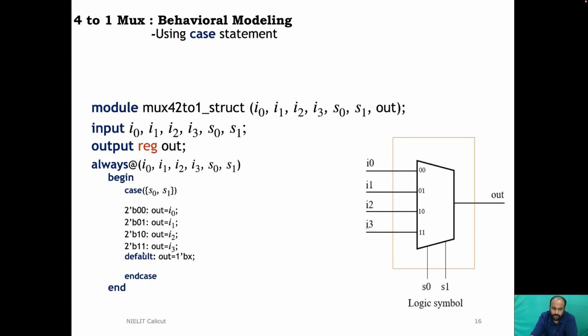Here you may understand the importance of giving 2'b, because if you are not giving 2'b here, this 10 may mean ten, because the default base in the number system is decimal. So it's very important that you give 2'b so that the compiler knows clearly it's a 2-bit number to expect from the input, and it should be in binary format 10. So when the user gives any of these inputs 00, 01, 10, 11, the corresponding output will be given to the output.